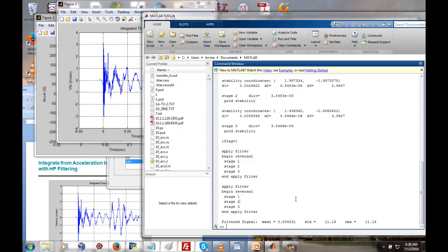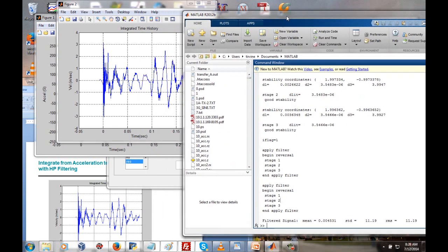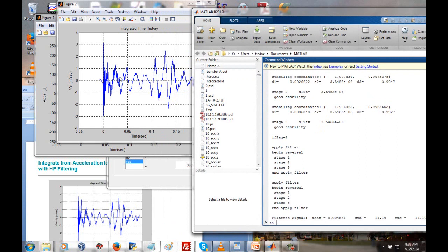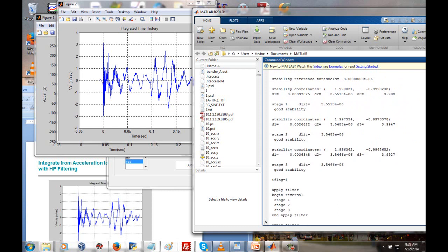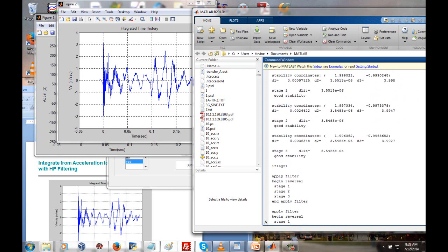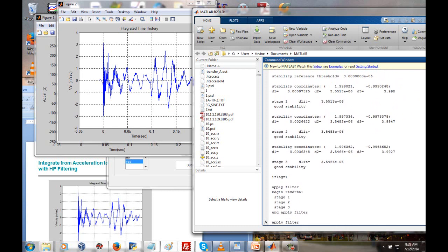removals. One thing we also need to check, when we have this high amplitude, high frequency shock data, we probably have a high sample rate. And if we're doing anything with low-pass filtering, it's a good idea to double check the filter stability. And this has to do in part with the precision of the numbers, with significant digits and so on.